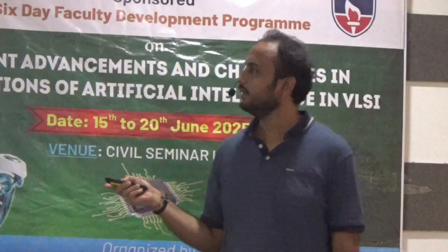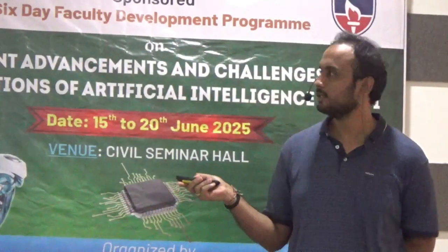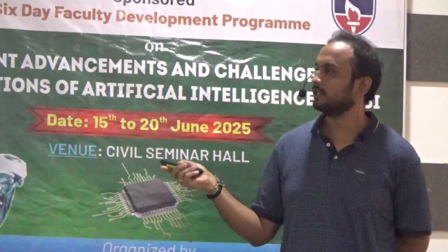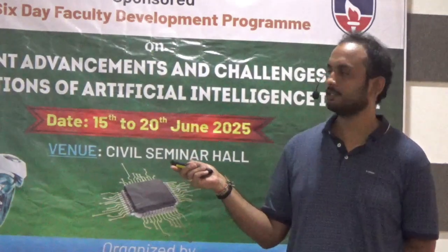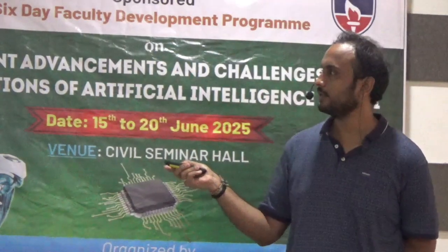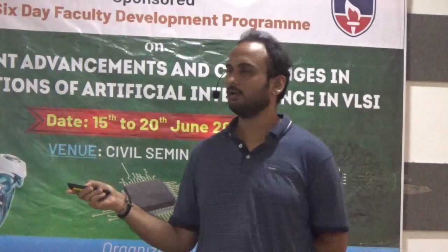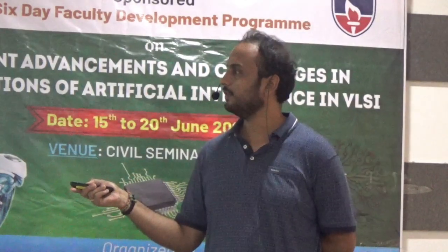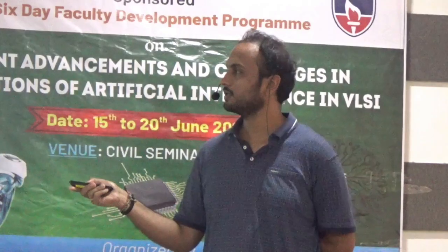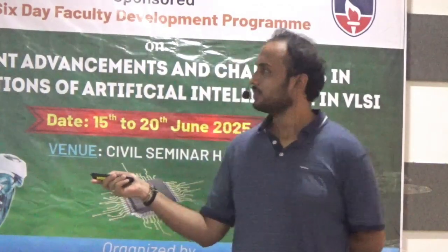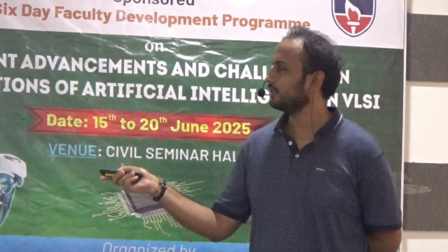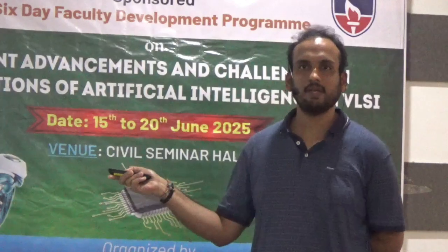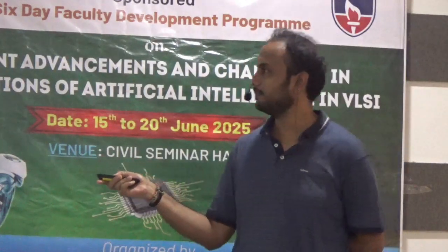So this is a very fundamental Shannon's law. Many of you have studied it in your communications course. It denotes what is the maximum channel speed with respect to the bandwidth and signal to noise ratio. So if you take an example of Wi-Fi 6, considering the data rate and the bandwidth, and let's assume the signal to noise ratio to be 10, you will find out the maximum capacity you can achieve is 0.5 Gbps.